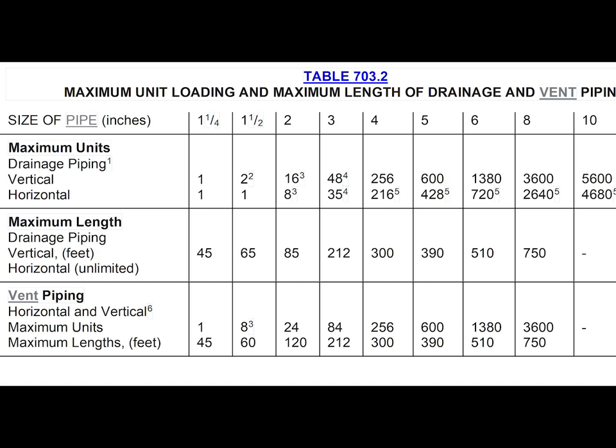Individually, A has 9 fixture units, one of which is a water closet, a toilet, resulting in a 3-inch drain pipe. B is simply the kitchen sink and dishwasher with 2 fixture units, so it has a 2-inch drain. C is only 6 units, which would normally be a 2-inch pipe, but since there's a water closet on the line, this drives us to a 3-inch pipe.